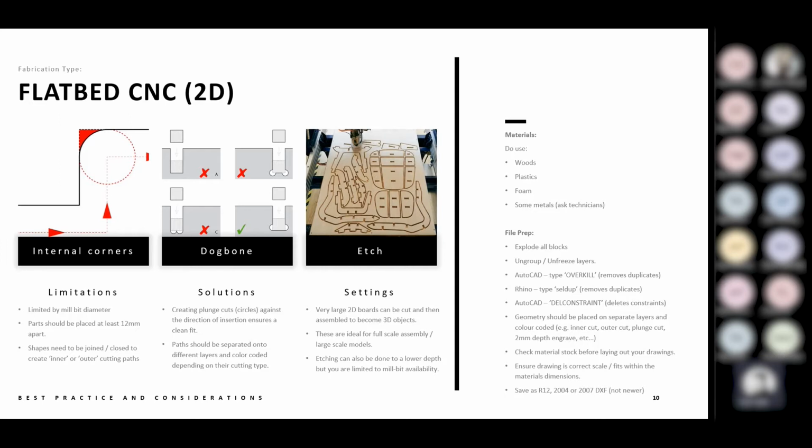Same file prep as before. Explode all your blocks, ungroup and unfreeze your layers. If using AutoCAD, use the overkill to remove duplicates, or use delete constraints to delete your constraints. Make sure your drawing's the correct scale. Check the material stock before you send it for fabrication. And of course, make sure you're talking to the technicians.